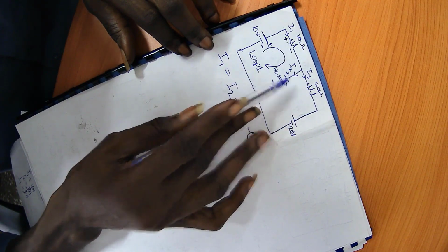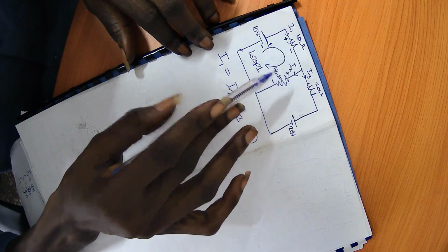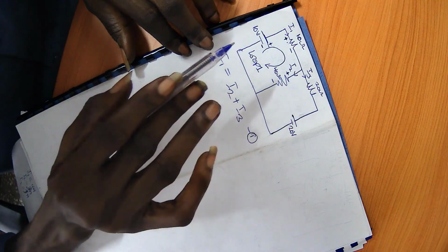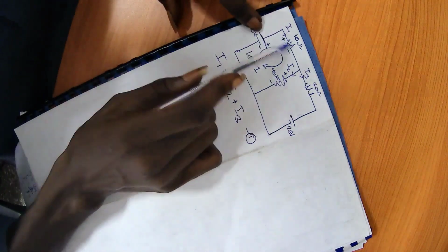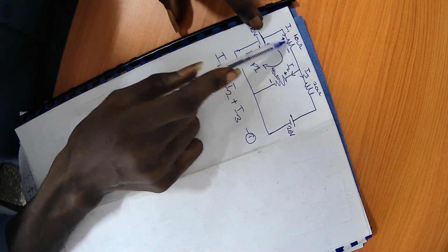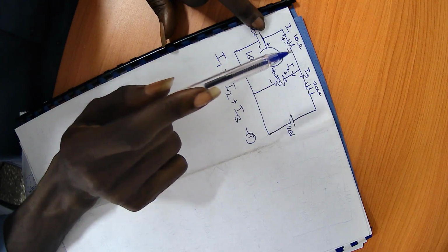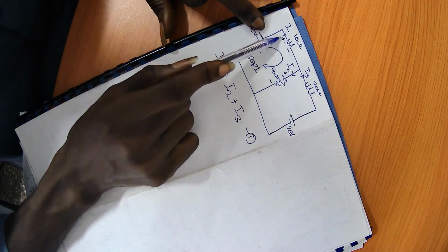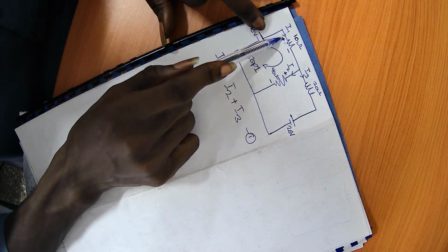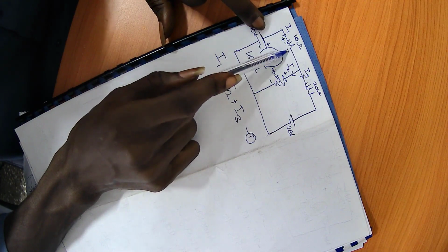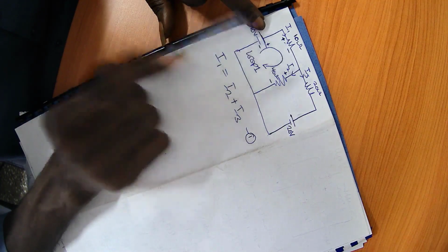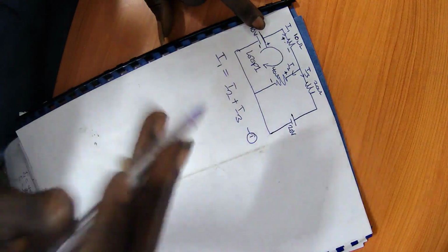If they are in the opposite direction, that means that there is an increase in voltage and that particular voltage will be positive. So now first, in this particular resistor, you see that the current and the loop are in the same direction. And also, you can see that the current is starting from the positive and it's coming to the negative. That means that the voltage is decreasing. That's a voltage drop in this particular resistor.